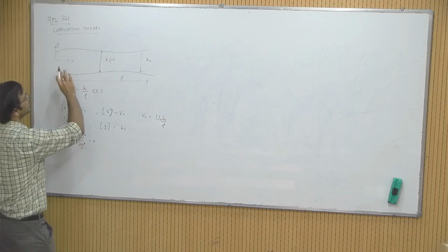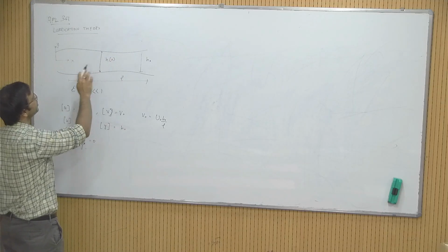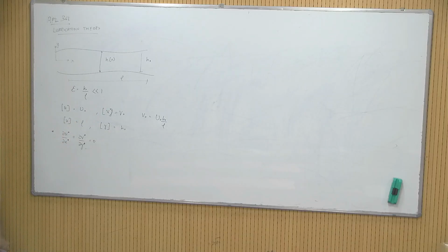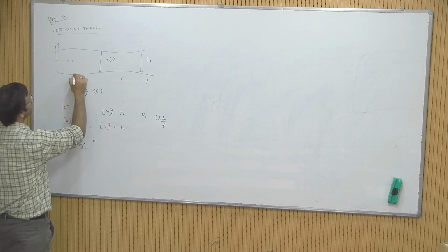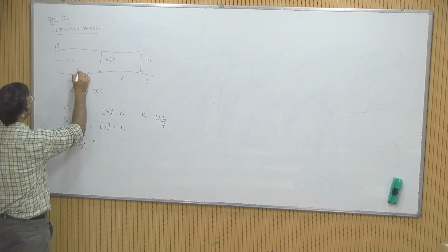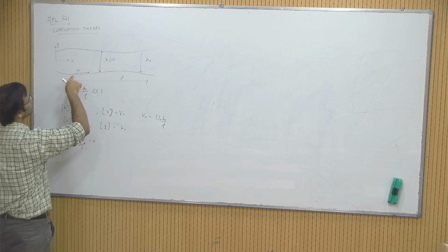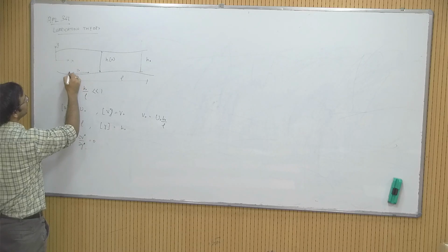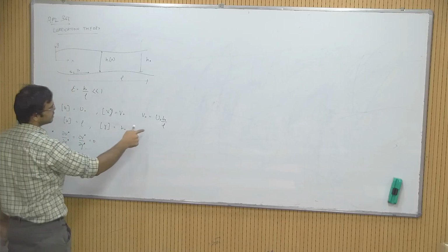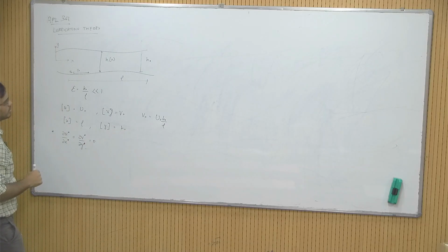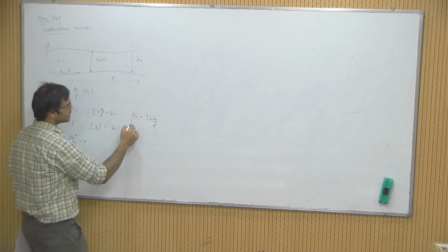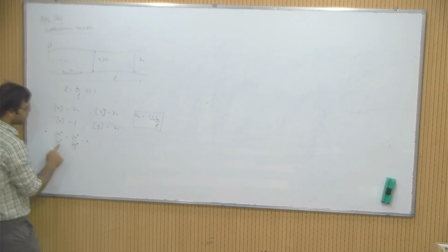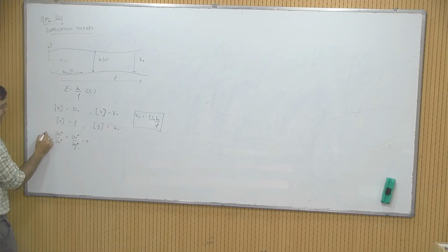So, we said that any y direction velocity is actually due to the deflection of the walls. If these walls were straight, there would not be any y direction velocity. So, if you have some x direction velocity which is u naught, and the flow direction is very close to the wall, let us say the flow direction is in the direction of the walls, then you can say that v naught by u naught is approximately h naught by L. That was our idea of deriving this scale of y direction velocity, and from here we concluded that no epsilon remains even in your dimensionless continuity equation.